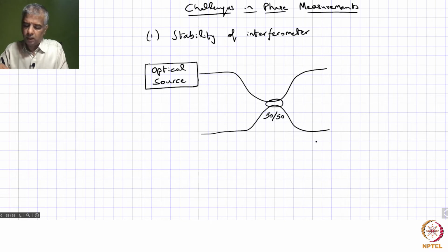Right? So, well, how does it work? We're not going to spend much time on it right now, but I can tell you quickly that essentially you have the cores corresponding to two fibers. They are brought very close to each other such that the evanescent field of one waveguide is overlapping with the evanescent field of the other waveguide, and so you are able to leak light from one waveguide to another waveguide and back, of course.